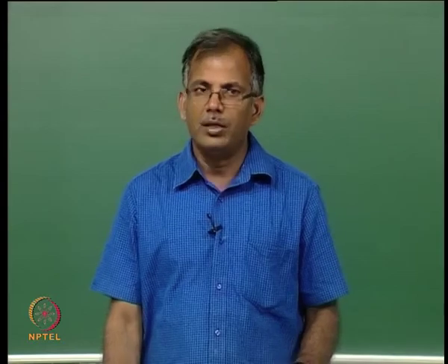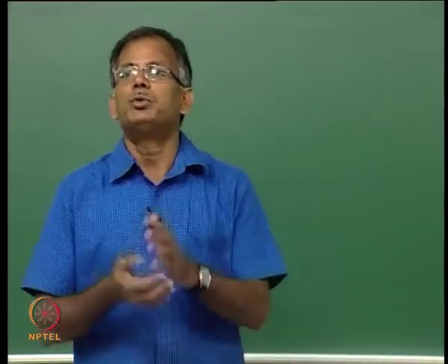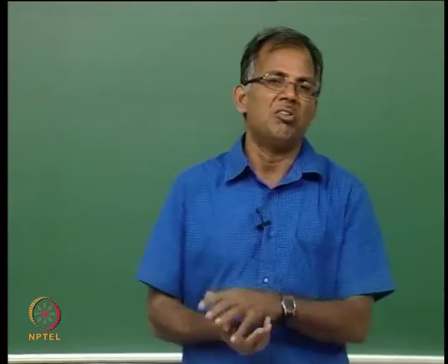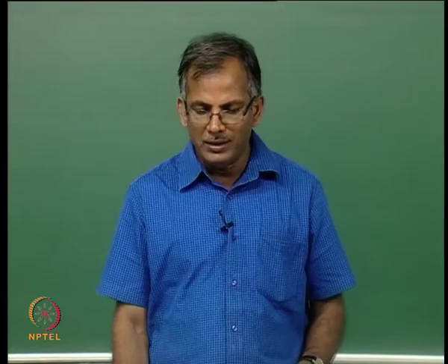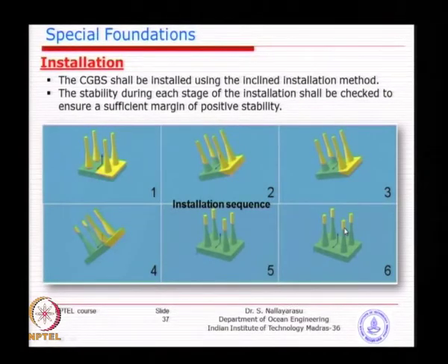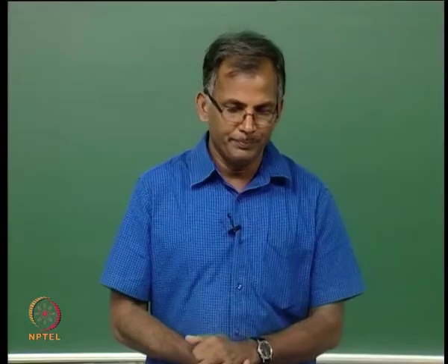Now imagine the wave loads at that time could be smaller, because you are not going to install this in a very high sea state. So now you need to look for permanent ballasting. In addition, for the 100-year storm condition, the horizontal load could be substantially larger. That is the time you do a solid ballast at the bottom, which makes the structure heavier, and also install the superstructure. This delta weight you are adding will compensate for the overturning coming from horizontal loads of wave, current and wind.